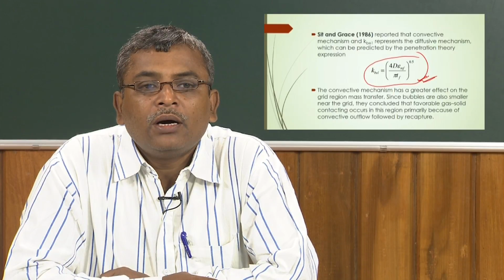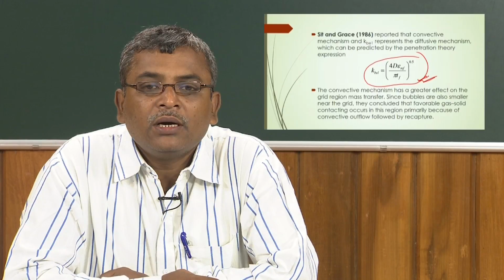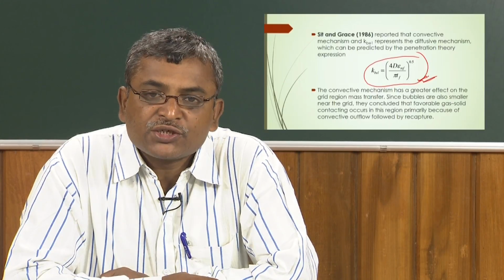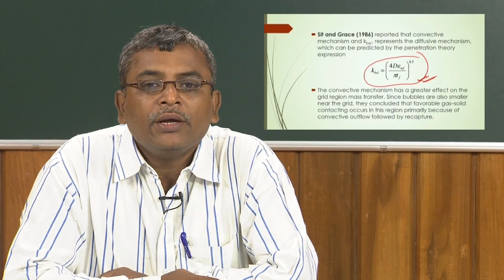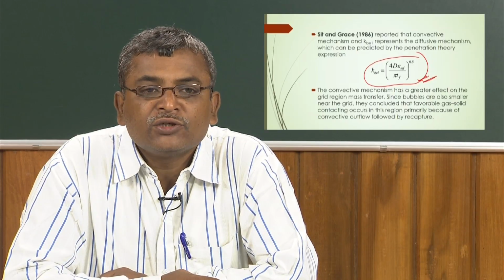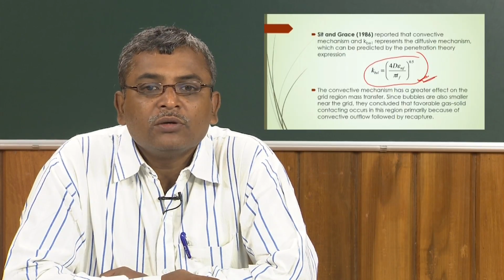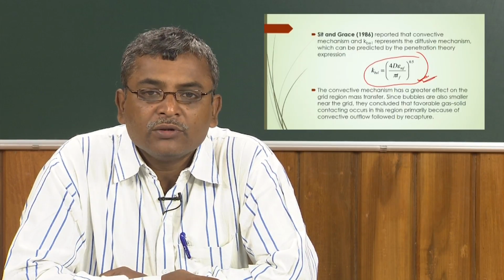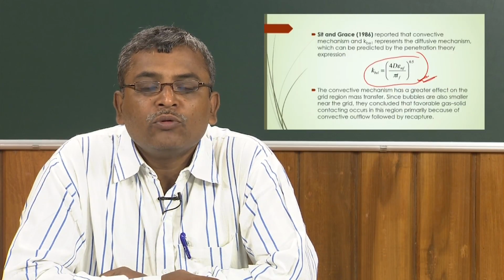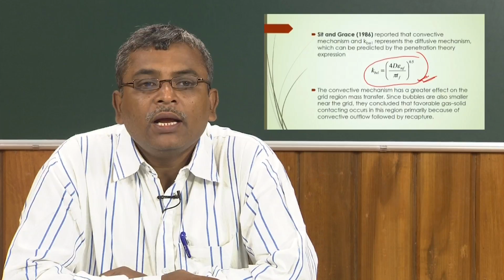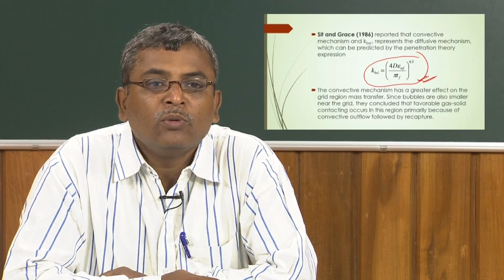We have seen that a bubbling fluidized bed will give you more mass transfer if the Reynolds number is greater than 80. Even in the grid region, the mass transfer coefficient will be higher, because there will be a high velocity, and also due to bubble breakup more smaller bubbles will be there, and then the transfer from bubble to the emulsion phase will be more.